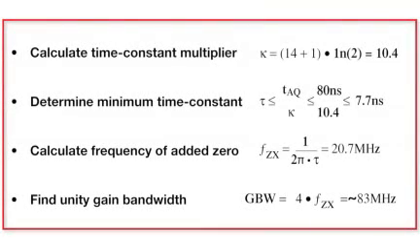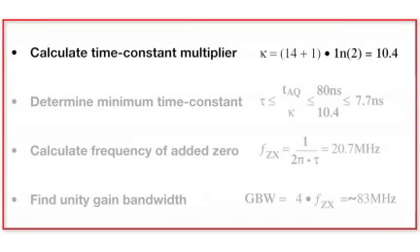This is the procedure that shows us how to calculate the minimum unity gain bandwidth of the op-amp that can support the ADC based on its minimum acquisition time and our rules of thumb for the RC filter network and good op-amp stability. We first calculate the value of K, which takes into account N, that is, the resolution in bits for the ADC. For ADS7945, this N is equal to 14. And then we calculate tau, which is the acquisition time of the ADC over this constant K.